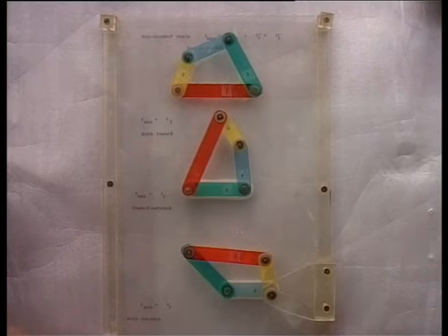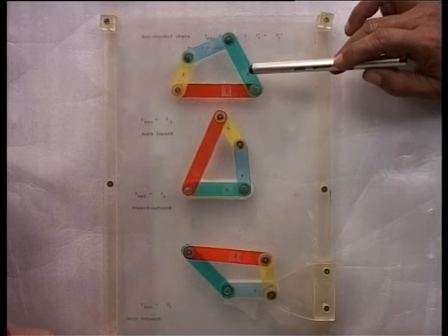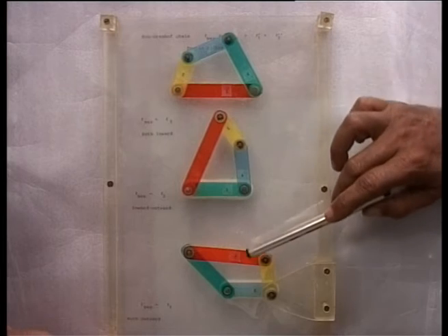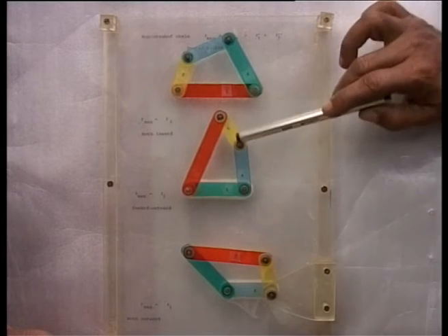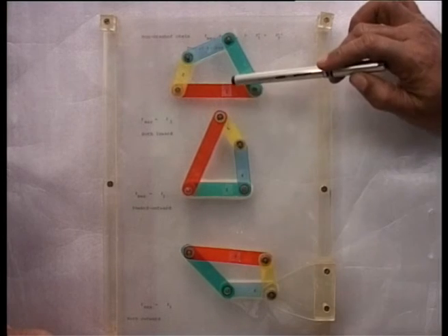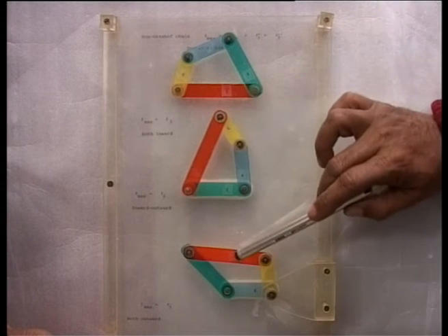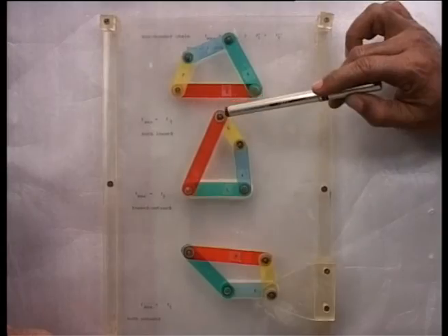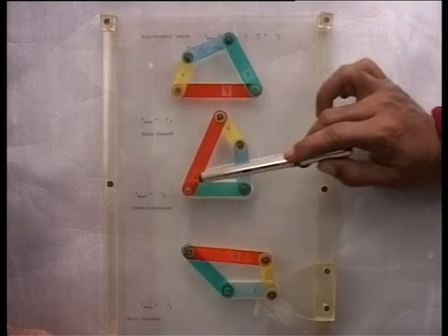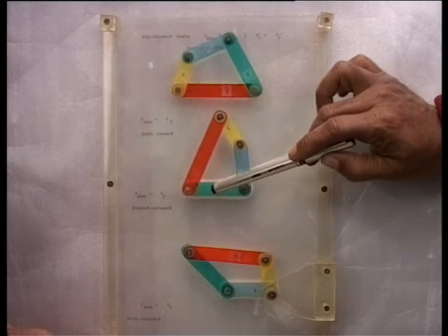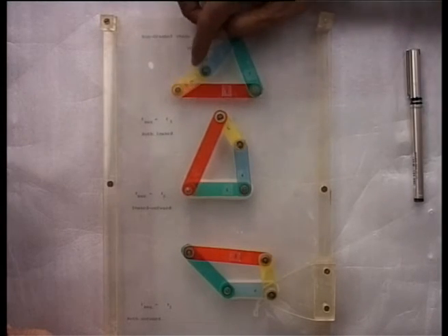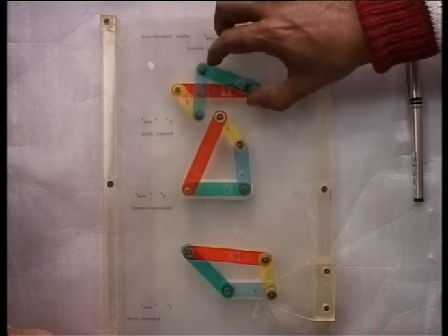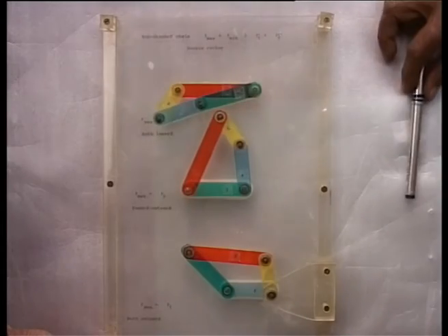So, now we see all the three models from the same non-Grashof chain. Link lengths in all these models are equal; the only thing is the longest link is positioned differently. Here it is frame, here it is coupler, and here it is connected to the frame. And all these inversions have produced, as we have seen, double rocker linkages.